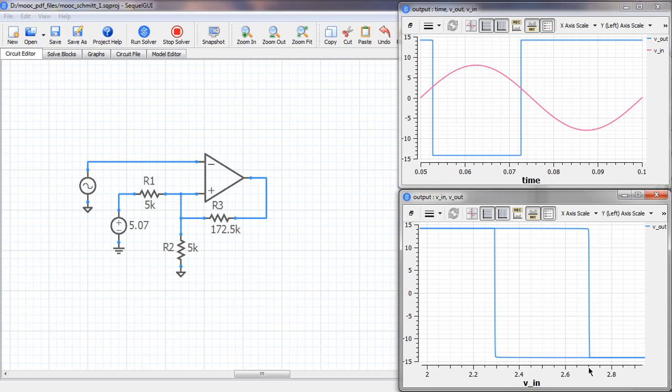And we now need to check two things. One, delta VT, that is the difference between VTH and VTL, should be 0.4 volts. This is 2.7, this is 2.3, so the difference is indeed 0.4 volts. Second, the center of this interval, which we have called as V0, should be 2.5 volts, and that is also observed over here. So that shows that our design is correct.